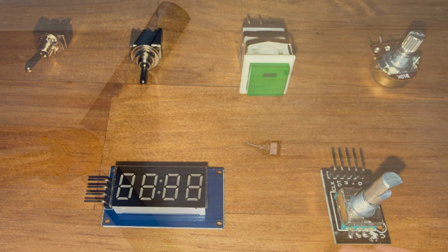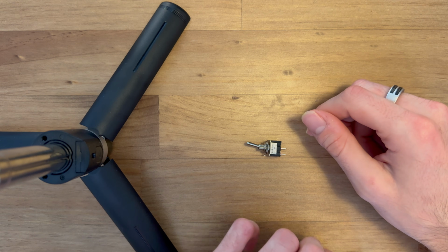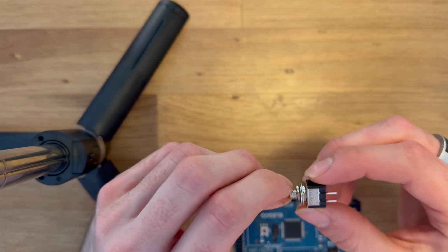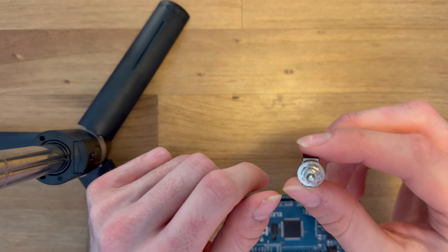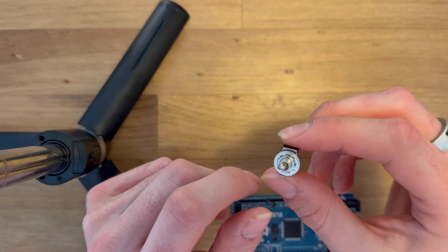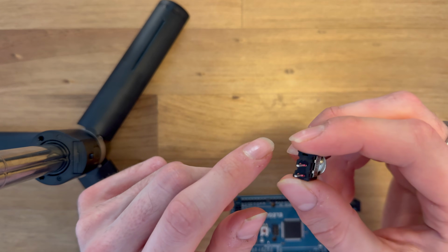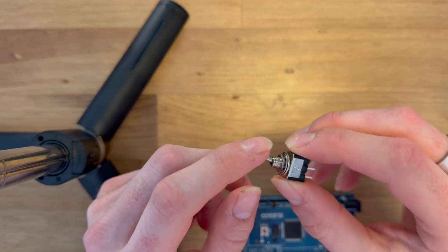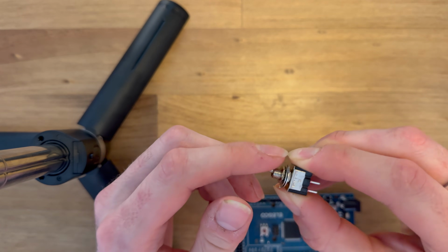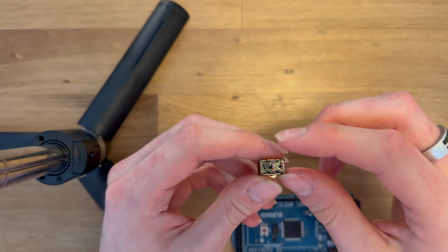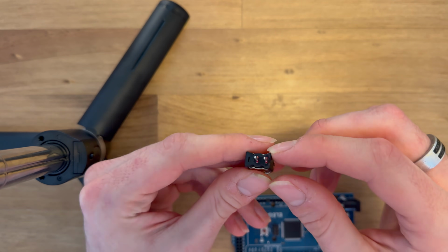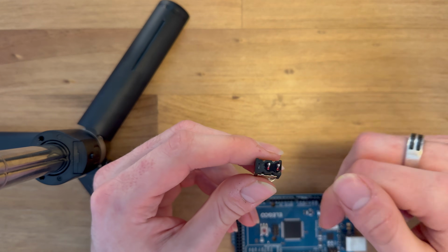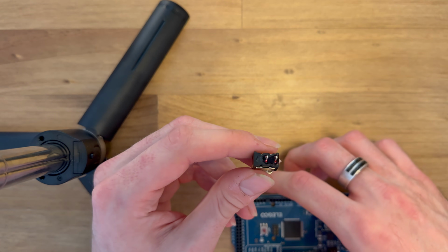Let's get started. So the first component we're going to wire into the board today is just the standard on-off toggle switch. This example is a miniature version, but it's exactly the same for a larger version as long as it's got 2 prongs on the bottom. A simple on-off switch, so just moves like that. And 2 prongs, one of them is a ground, so a negative connection, and the other is a positive connection, which goes into the digital pin on the board.